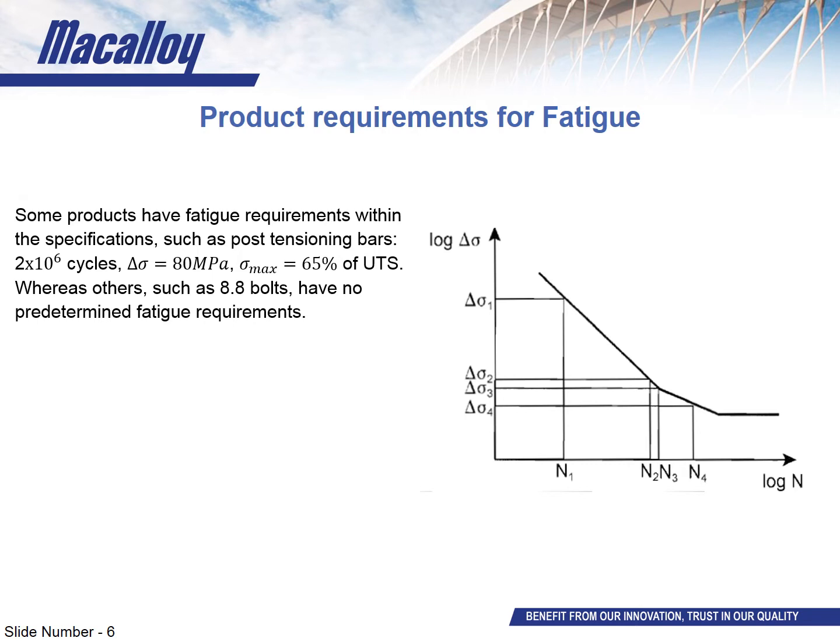You can compare the stress range on a material against the likely number of cycles to failure using an SN curve if the data exists for the product that you're looking at. You can see an example of this on screen now. This graph can give an approximation of how many cycles a component is likely to withstand, found on the x-axis, when subjected to a given stress range that's found on the y-axis. This data is plotted using a logarithmic scale to keep it on a straight line and easy to interpret, but don't worry, I'm not about to kick into a maths lesson.